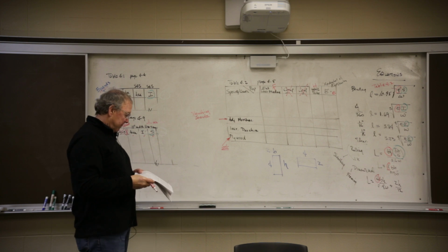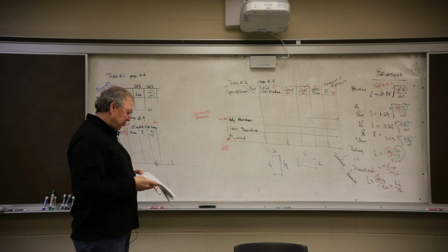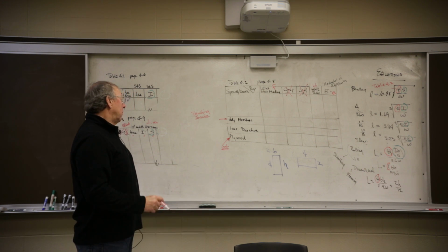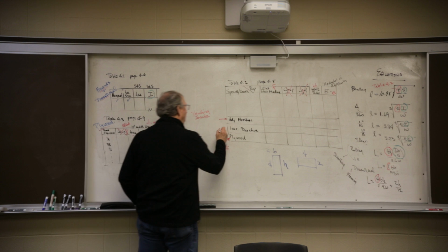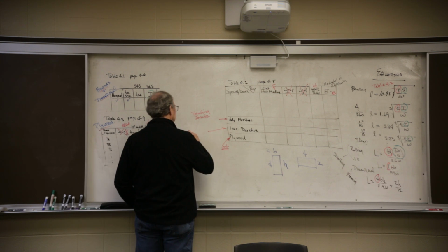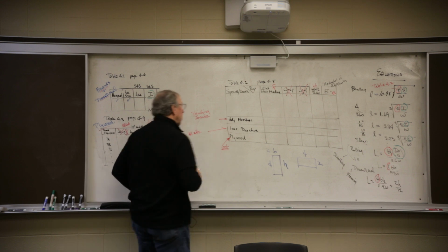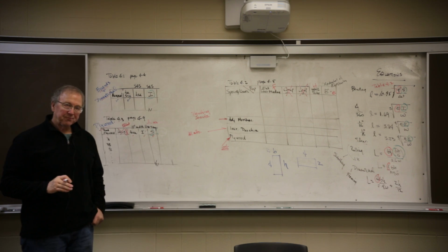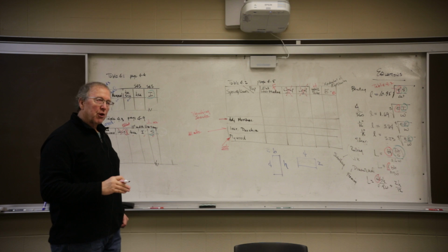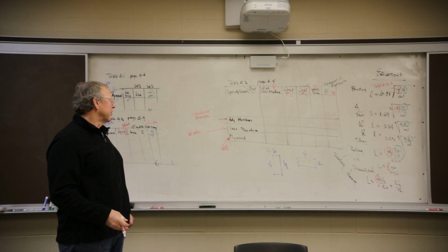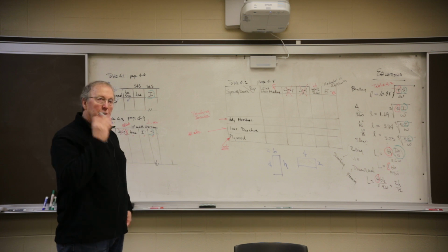Okay, the next one. Increase for load duration. 7 days or less permitted for lumber and plywood. So this is going to be all materials. And how do you know? If we're going to use it once and throw it away, we can use this duration increase.